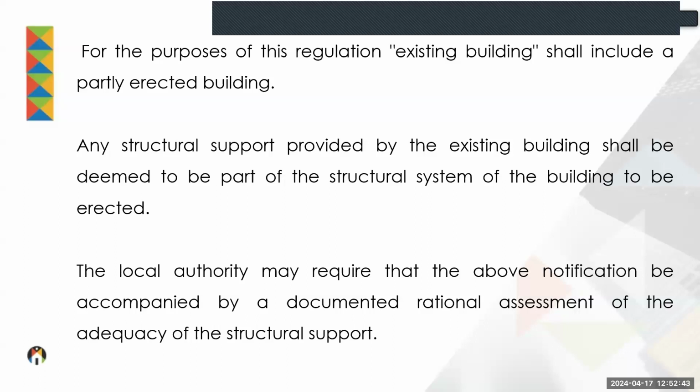What if it's a partly erected building? You know, the Building Regulations and Standards Act does put timeframes on the completion of buildings. And if there is a stop in construction for a period exceeding a certain time, it needs to be submitted then as a new building. So in this case, it will be regarded as an existing building, and an assessment report on the half-completed structure also needs to be submitted.